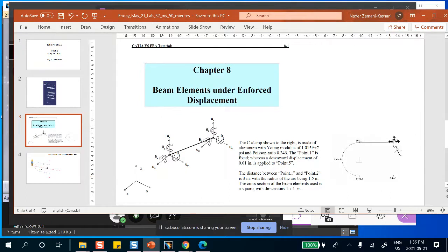Wireframe is not a sketch. It's a bunch of lines and curves and points and perhaps splines and things of that type in space. And you're going to solve it like that, which is more involved. However, sometimes you may not have a choice, okay? Because if your frame structure, such as this, cannot be put in a plane, then obviously you cannot have it as a sketch, because a sketch is a two-dimensional plane, okay?